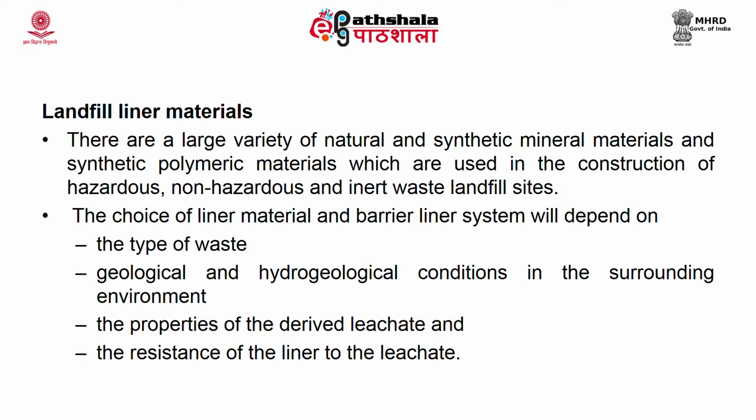So, some of the materials are corrosive, which can corrode the liner material and destroy, puncture or create holes in it so that the leachate can be released. So, the property of the leachate which is generated needs to be determined. You collect the leachate, characterize it, find out what materials are there and how corrosive it is, and then you decide the liner material.